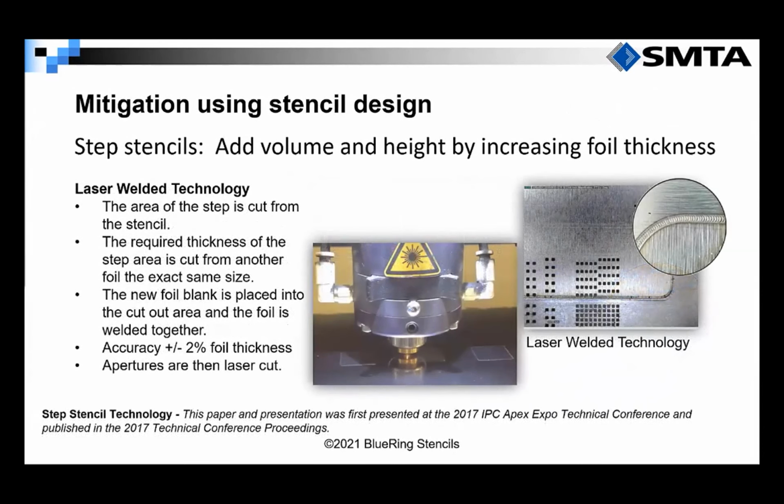Laser welding technology is utilized for the largest percentage of step stencils in North America today. These lasers are extremely accurate, and the foil being welded is very accurate as well. I would estimate that 90 to 95% of the step stencils our company produces are welded steps. So how does this work?